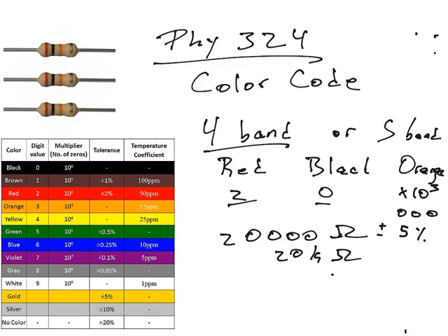And of course, the better tolerance you have, the more accurate this reading is going to be, the better the element is, and thus the more expensive it's going to be. If you need very, very high precision equipment, then you're going to pay more, and you're going to have tolerances of about 1 or 2 or 0.1% or things like this. Typically, the regular kind of resistors you're going to buy in a normal circuit lab will have gold stripes or silver stripes, because you don't have to be that perfectly accurate. But that's how you read off this color chart.